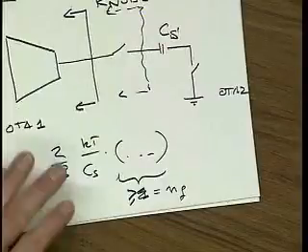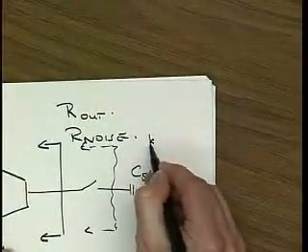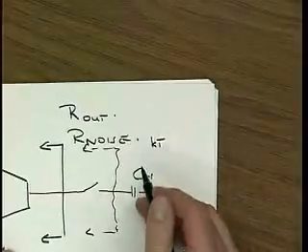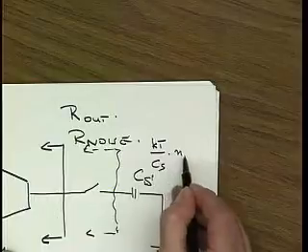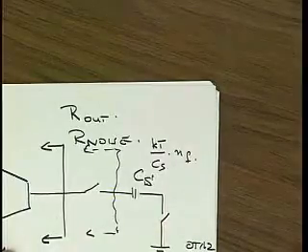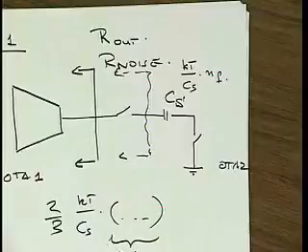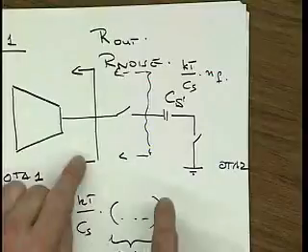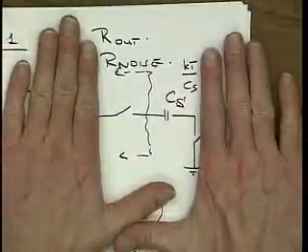And so the noise sample that we get here, the variance of the voltage on CS due to noise, is really kT/CS times some factor, NF. Now, it's quite interesting. If you sell an A to D converter, and it's built in CMOS, which is the most likely choice, then the input of the A to D converter is also going to look exactly like this.